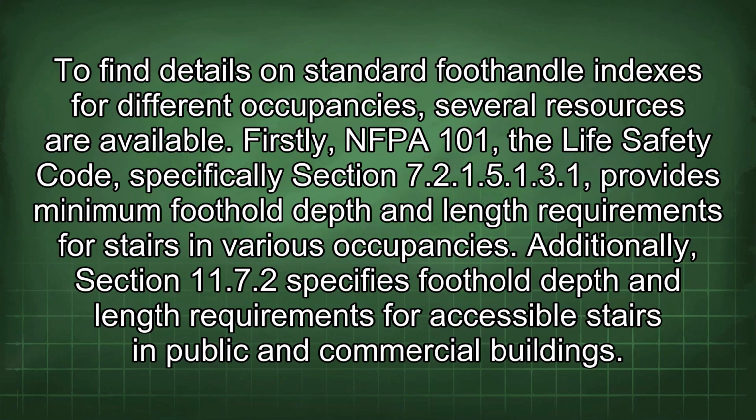To find details on the standard foothold dimensions for different occupancies, several resources are available. Firstly, NFPA 101, the Life Safety Code, specifically Section 7.2.1.5.3.1, provides minimum foothold depth and length requirements for stairs in various occupancies. Additionally, Section 11.7.2 specifies foothold depth and length requirements for accessible stairs in public and commercial